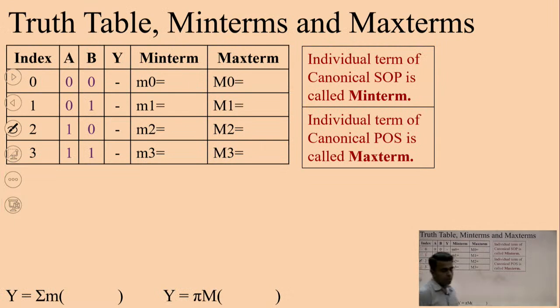Now we are aware of how we can convert a non-canonical form into a canonical form. Now relating these canonical and non-canonical forms with the truth table, I cannot relate non-canonical versions of the expressions with the truth table, I can only relate the canonical ones. So I am taking a two variable truth table in which there are two inputs A and B. These two are the inputs. There is a single output Y.